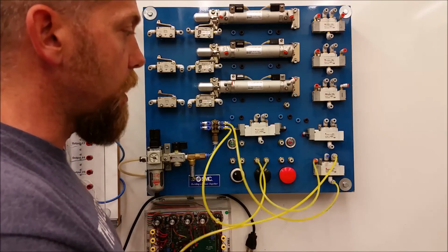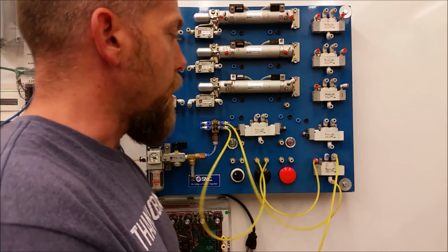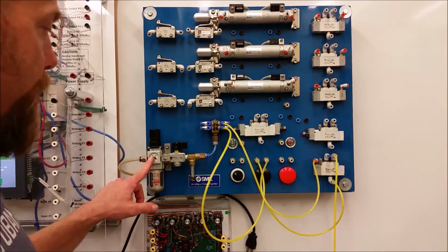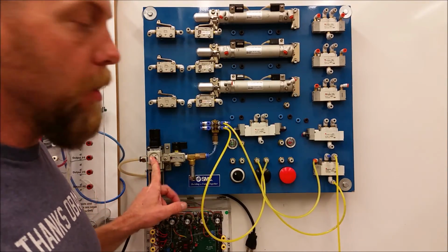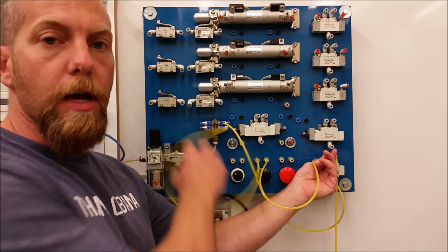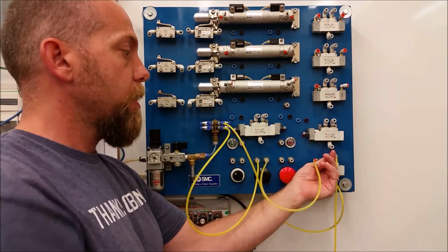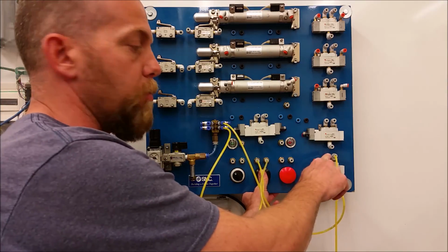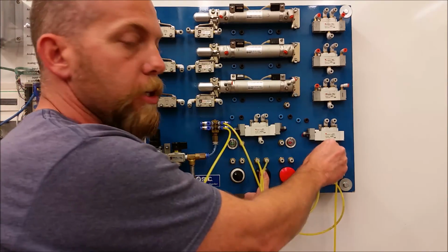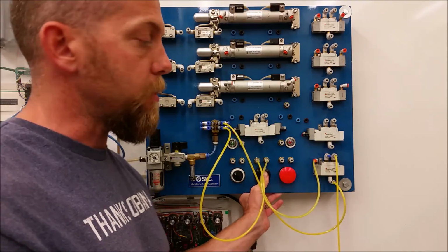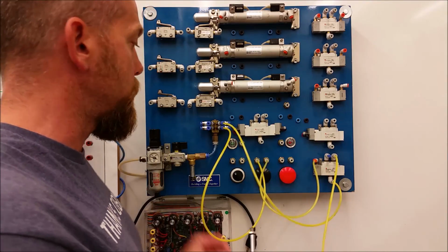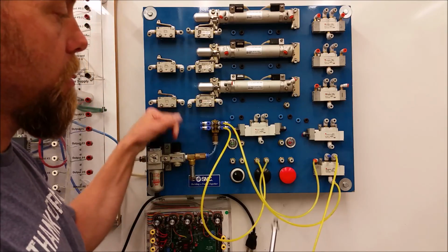Excellent. Okay. One safety note to take note of: you'll notice that we're putting this plug in here, and I only have about 25 psi, right? So again, don't be a donkey and put 100 psi to these boards. If you've got 100 psi and you just block it, you're asking this to block that 100 psi, and this could shoot out and take out somebody's eye. So again, do me a favor, don't be a donkey and put 100 psi to these boards. 25 to 30 psi is ample pressure.